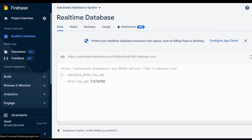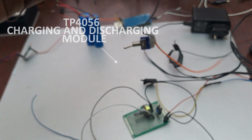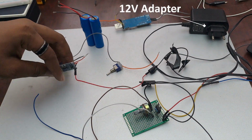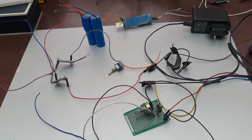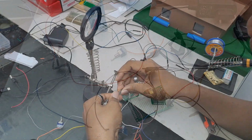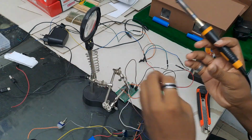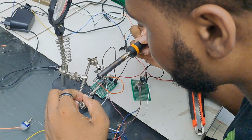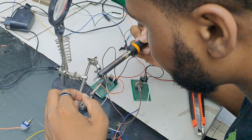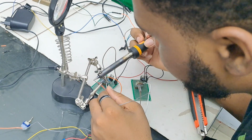You have a battery system, which would contain a charging and discharging module for the batteries, and you would have an adapter to supply 12 volts DC to those charging modules, but they would require a 5 volt supply, so you need a voltage regulator circuit to give a 5 volt supply to those modules. You would also need a lot of jumper cables, Vero boards or perf boards, a soldering iron, and tape. A lot of tape. You could use a solderless breadboard instead of a perf board. Well, these are generally the components that were used for this project.